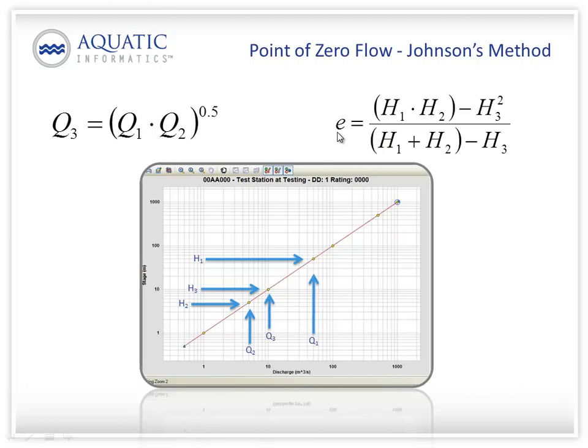And if we're just developing a curve for the first time, often we don't have a good idea of what the rating curve should look like to begin with. And so this method is often prone to producing offset values that are unrealistic, that just don't make sense in terms of the geometry of the stream or the hydraulics of the stream.